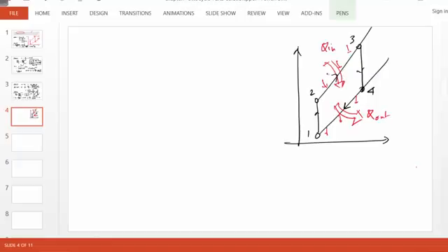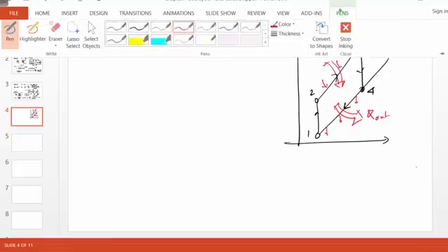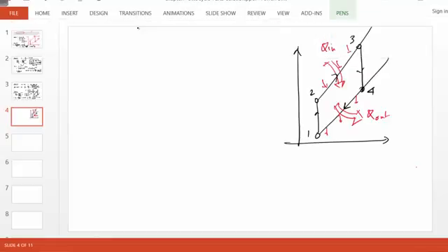And it's relatively easy to figure out Q in and Q out. So therefore, we will not calculate W in and W out, because we know Q in is what? We have already developed the formula, but it's obvious. A closed volume of gas is taken from 2 to 3. So it's simply delta U because there is no work. And that's m Cv (T3 minus T2). So if we substitute the values, our mass is 5.9 times 10 to the minus 4.